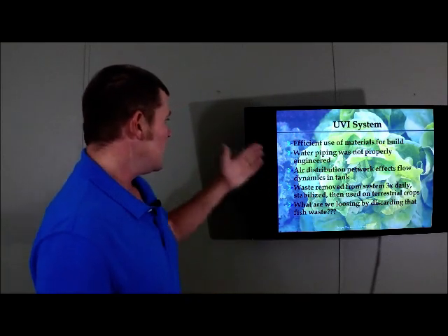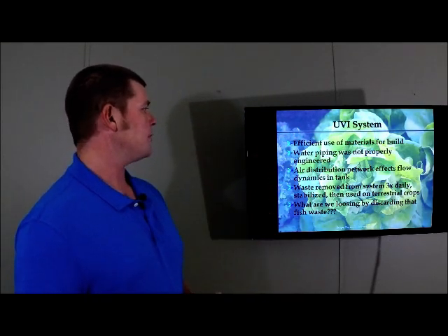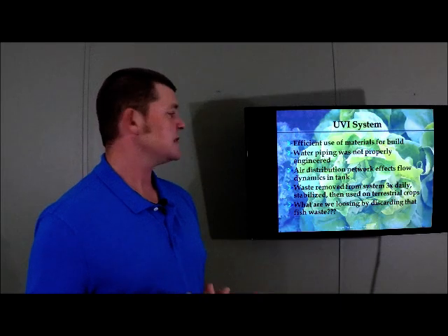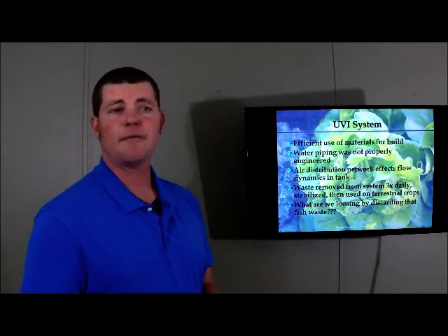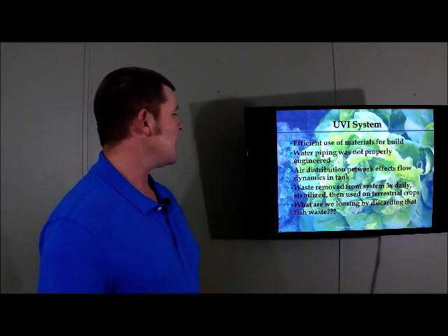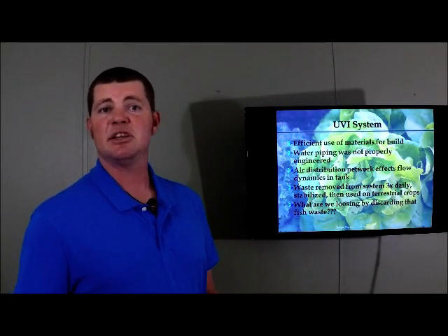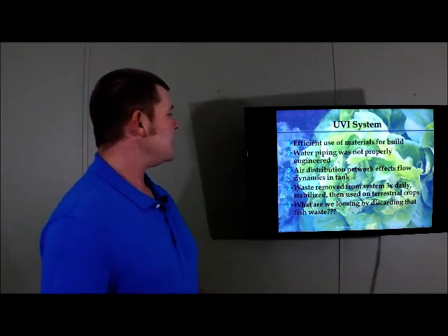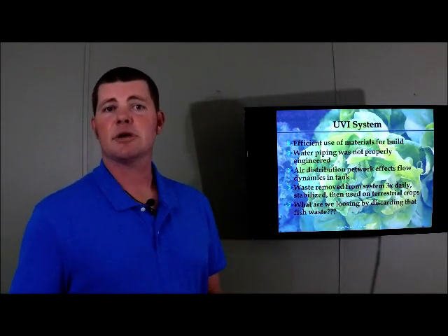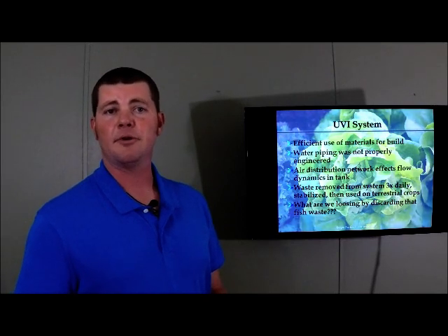The waste is removed from the system 3 times daily through those clarifiers. And it's stabilized in a pond. They dug a pond, lined it, and have some air stones in there. So very similar to a mineralization tank. Then after it's stabilized, they use it on terrestrial crops that are grown there at the university.